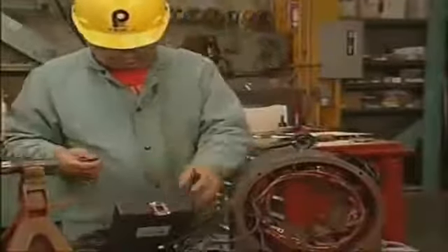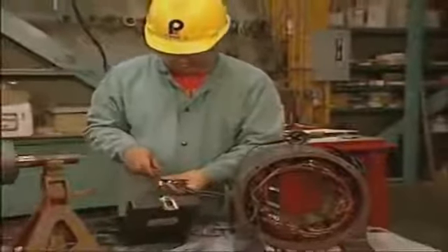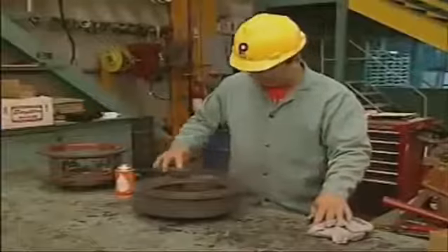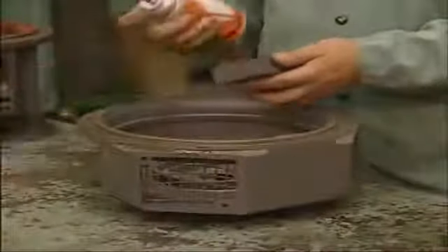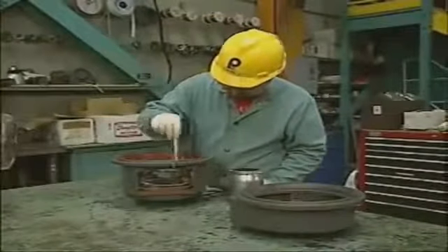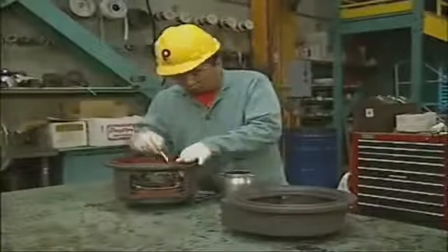Next, the field coil should be tested for grounds. This test is covered in this unit in the troubleshooting part of the motor maintenance topic. The end bells should then be checked for burrs and dings, and any that are found should be removed with a file or a buffing stone. The entire machine surface of the end bells should be brushed carefully with a wire brush or with a buffing stone and lubricant. And the end bells and the bearing housing should be cleaned with an approved cleaning solvent and then set aside.